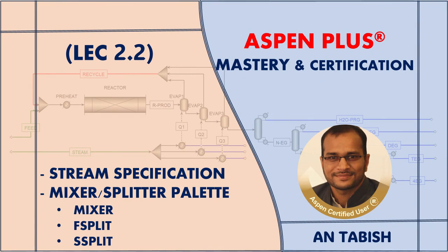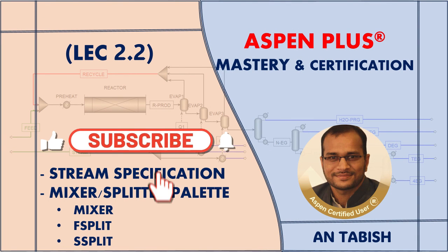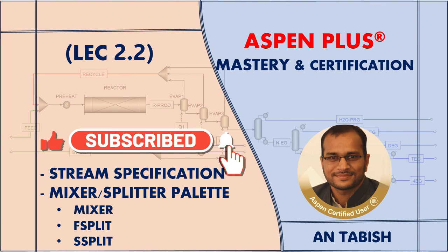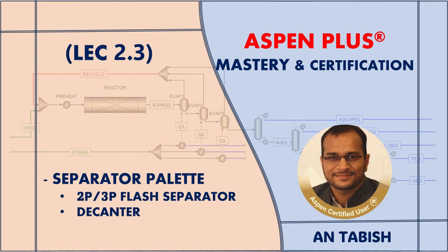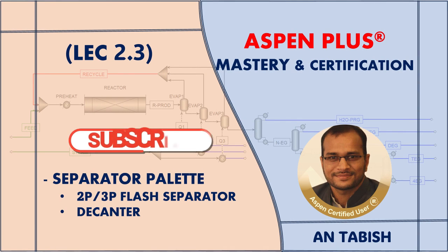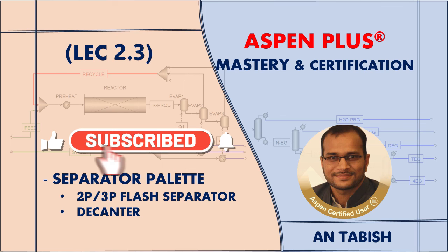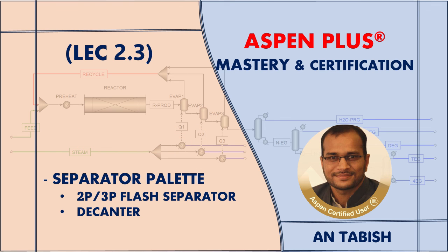So in this video we have learned how to define the specification of a process stream. Also we have learned how to simulate a mixer, flow splitter and the substream splitter. In the next video we will thoroughly cover the separator model palette with a specific emphasis on the 2-phase flash separator, 3-phase flash separator and the decanter.